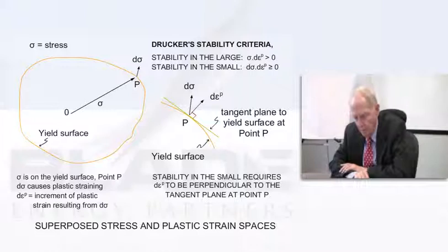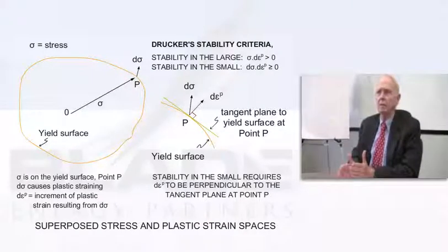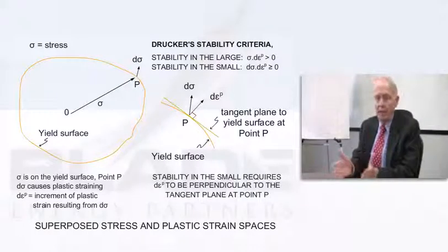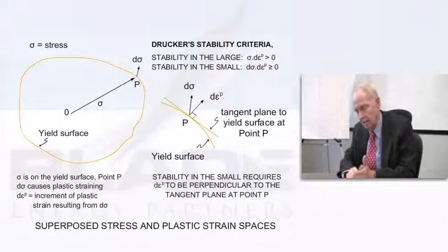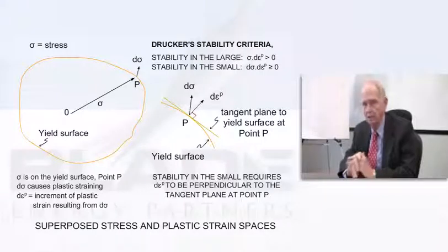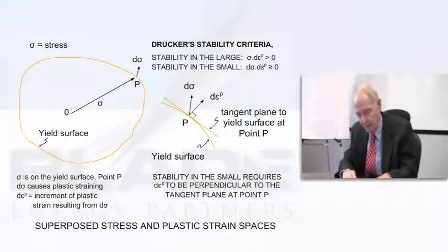And what I did is I went through it, and for each material that they tested, say a material like L80 from several different suppliers, I took the numbers and got the standard deviations and so on. And you're talking 5%. And these are samples sent by the steel companies to the project, so you know that's their best stuff, and the tests were carefully performed. But you see, there's a lot that sneaks in here.